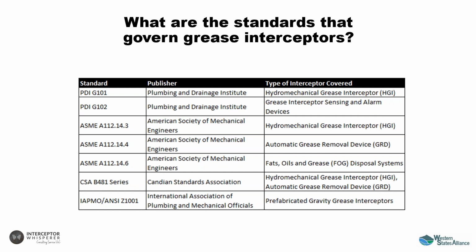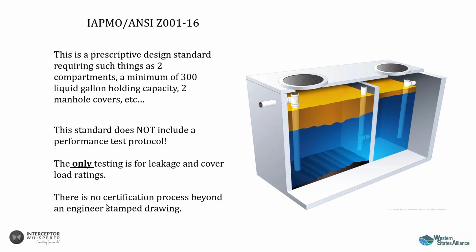So I'll touch briefly first on the IAPMO Z1001 box. For lack of a better term, this is a residential septic tank. Its design is based off of IAPMO ANSI Z1000, which is the residential septic tank standard for prefabricated tanks. And as you'll note here, it really just has a prescriptive design.